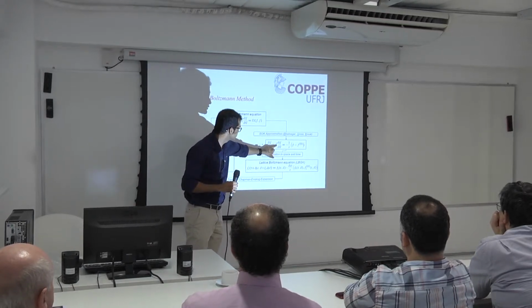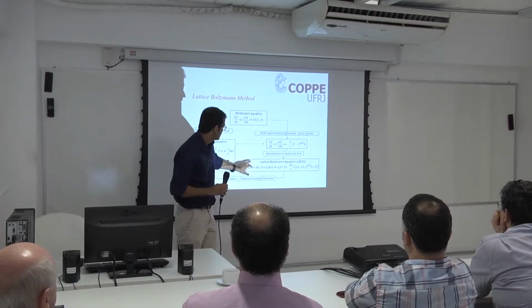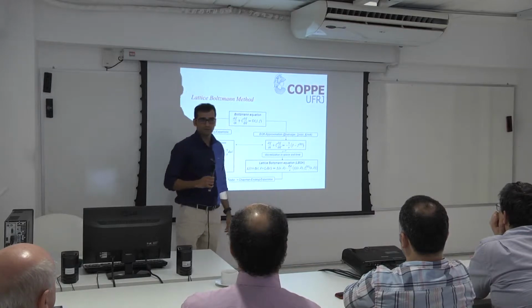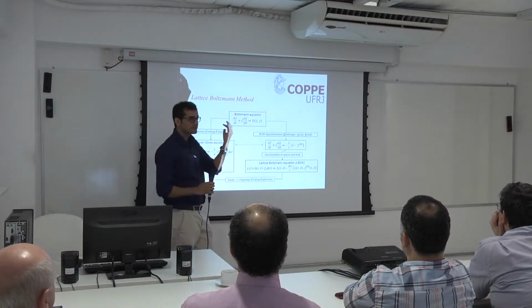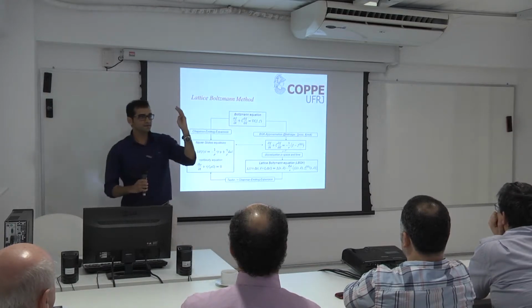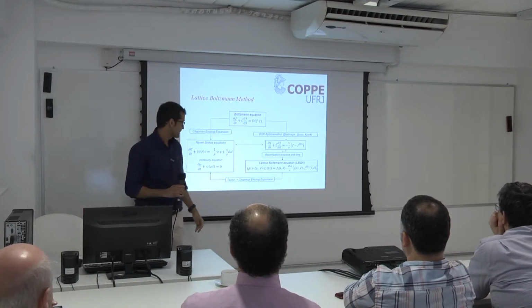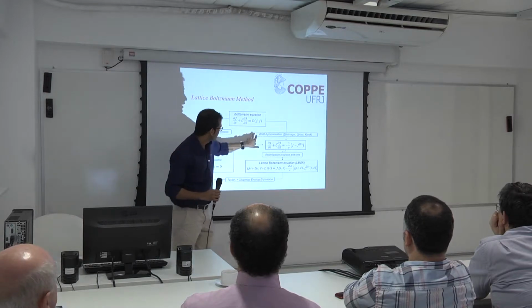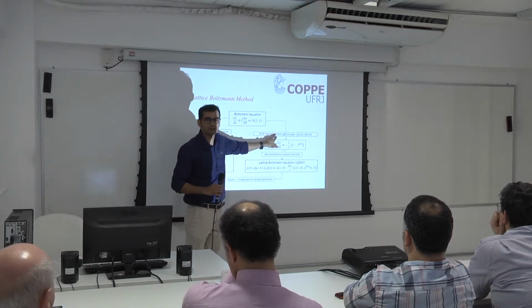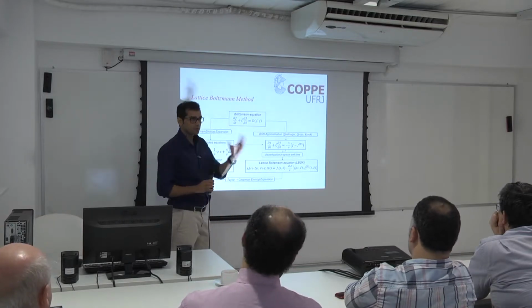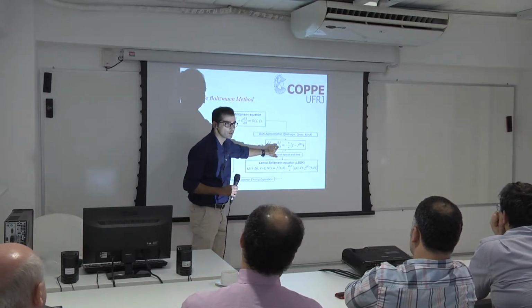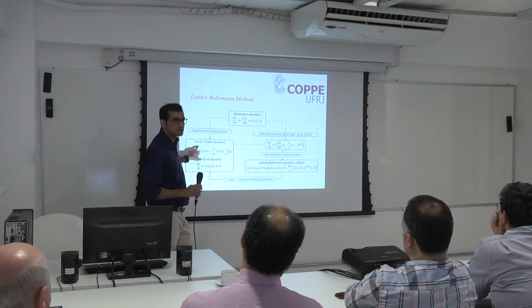After this, it turns into this, and then after this discretization, it turns into the Lattice-Boltzmann equation with the collision. So it has two operators functioning at this moment. One is streaming, one is collision. Now, you see, when you take into account the collision between the nodal points or the lattice points, pore or solid, you directly can approach the Navier-Stokes equation